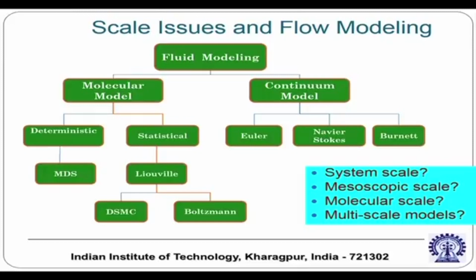The molecular modeling on the other hand can be deterministic or statistical. The deterministic molecular modeling, which we will focus on for this particular lecture, is molecular dynamics, and statistical approaches are also there. Two well known statistical approaches are based on the Boltzmann paradigm and direct simulation Monte Carlo, which are statistical tools.